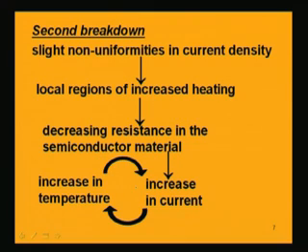Again, the temperature increase means the reverse saturation current also will increase. So, current will increase, and increase of current will again increase the temperature.